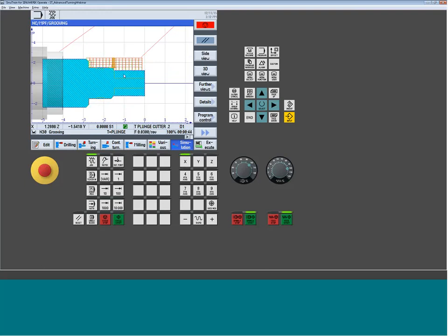But boy, when you're getting to strange irregular shaped grooves, it is just an awesome cycle to be able to leverage. So we see it here. It's working down through. That's the peck, 1/8 inch peck I did. And there's the finish. Finish, finish. So it's trying to kind of figure out its best strategy for how to finish based on if there's a wall there or not.